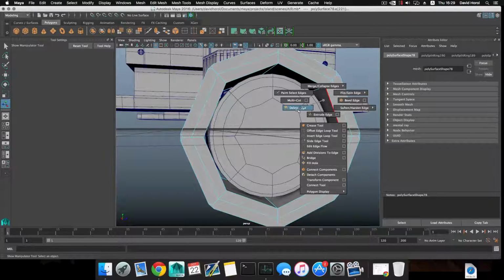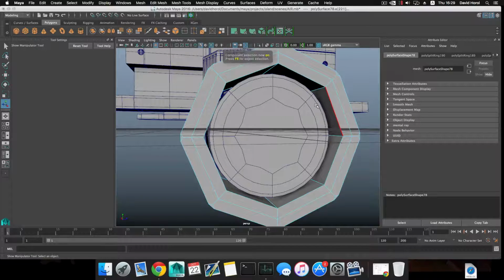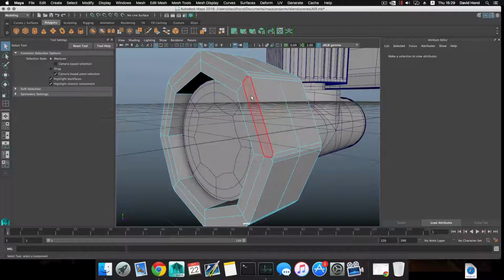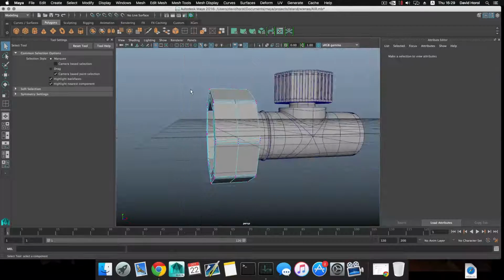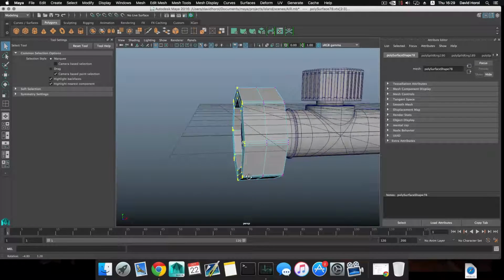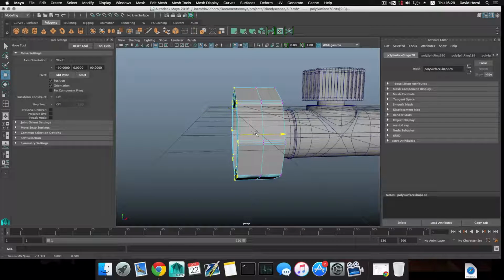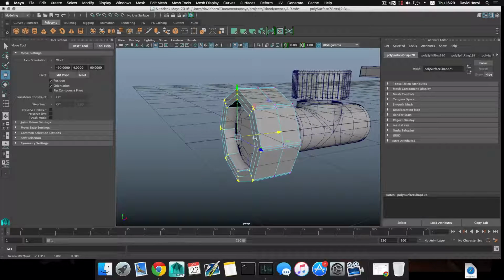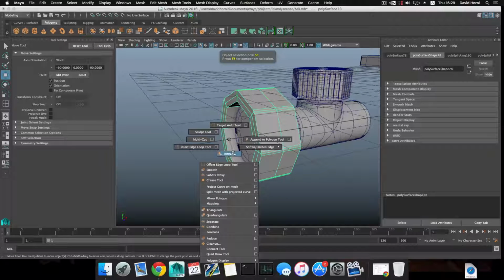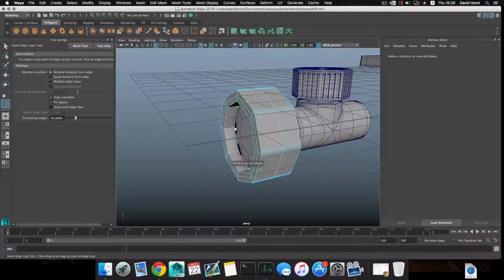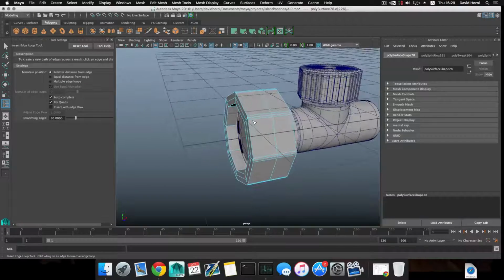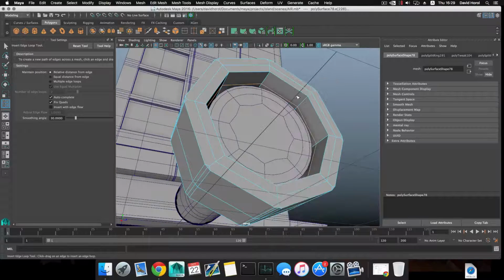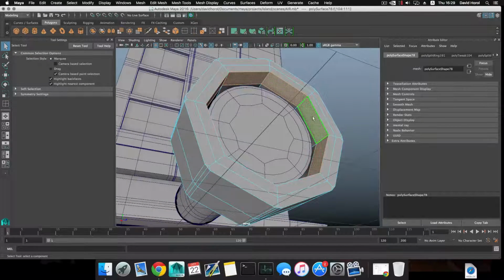We're gonna add edge loops. Sorry, press F8 to bring it back to object mode. Insert edge loops. No, before that, sorry guys. I'm gonna grab all these vertices here and move them a little bit like so. Outside, you see, outside of that, just a little bit, not too much. I'm gonna press F8, shift right click, insert edge loop. I'm gonna insert edge loop where that ends, like this is starting. And then I'm gonna do that. I'm gonna grab this, double click on that, delete.